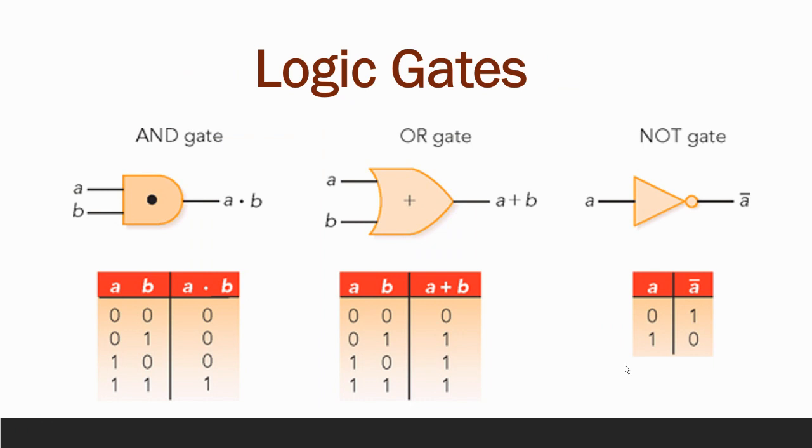We can use logic gates to represent the Boolean logic, as shown in the slide. The AND gate is represented by a rectangle with a round edge at the output side. We may add a bullet in the center to clarify it as an AND gate, though this is not necessary. Accordingly, the AND logic gate has its truth table as shown below the gate symbol.